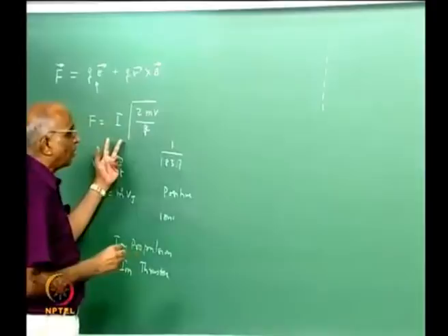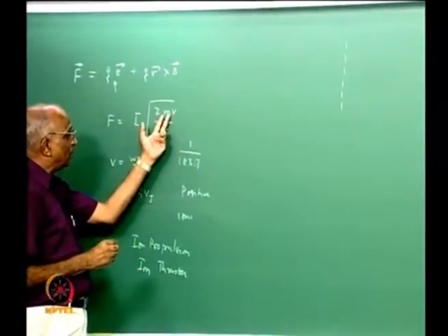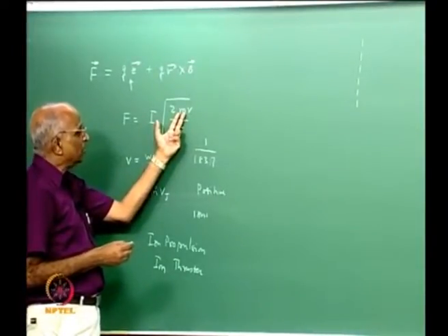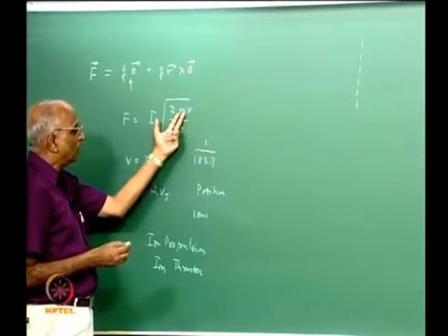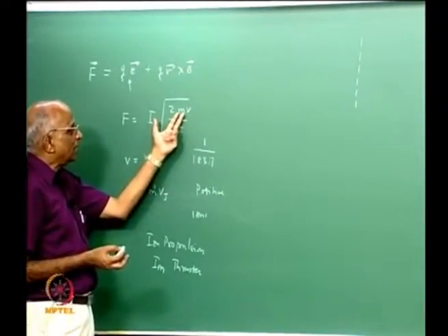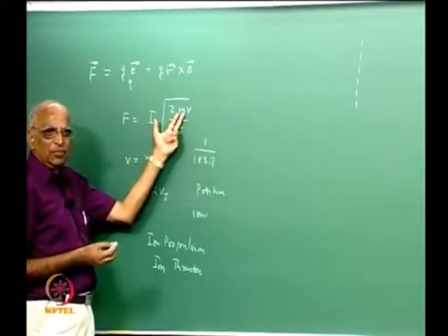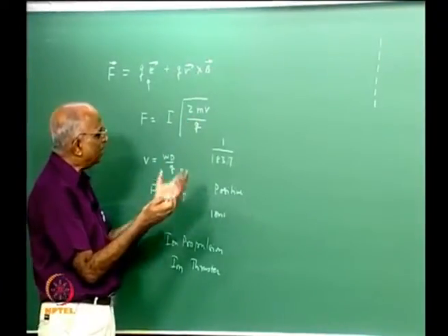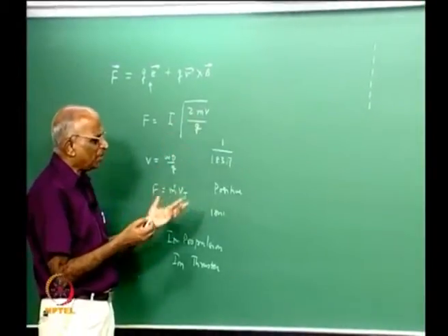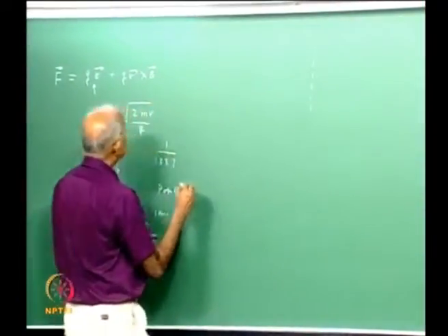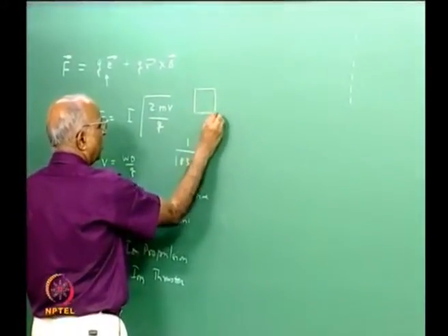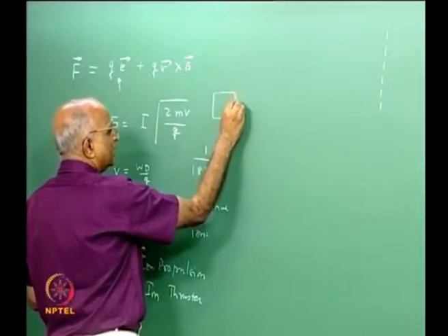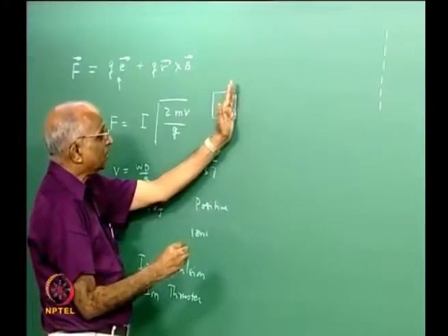Having said that, we also went one step further and said if I have to use this electrostatic principle and generate an ion rocket, now I call it an ion rocket because I know I am going to use positive charges, and we said yes, we would also like substances whose molecular or atomic mass is larger, so I would rather have heavy substances like maybe mercury, maybe cesium, maybe xenon. Mercury we said contaminates the surfaces of a spacecraft. A spacecraft consists of a lot of sensors, maybe an earth sensor, maybe a sun sensor, and these sensors are all glass type of things.